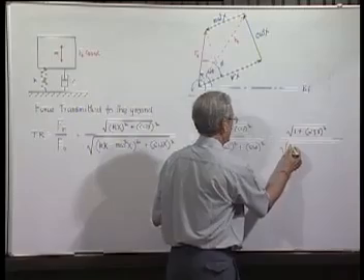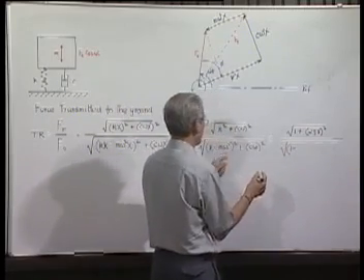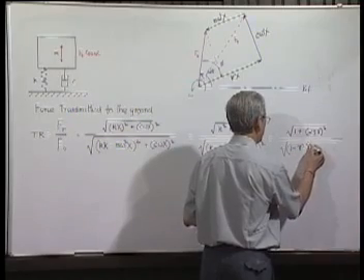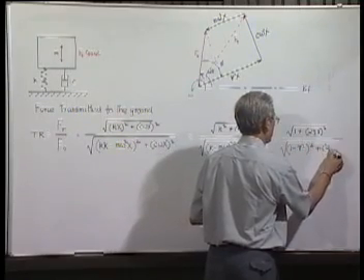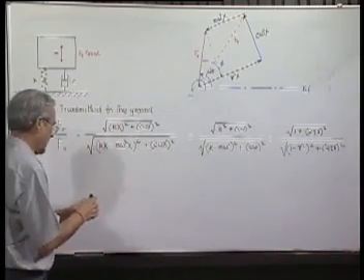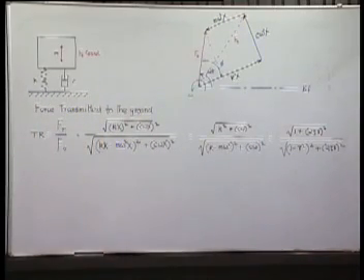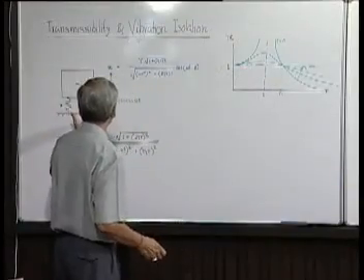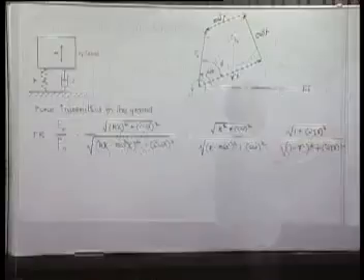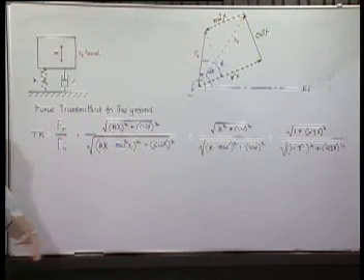This is 1 minus m omega square by k is omega square by omega n square, that is r square, and this is again. Thus, the expression for transmissibility, both from the point of view of transmission of motion or vibration or transmission of dynamic force, gives the same expression we find.